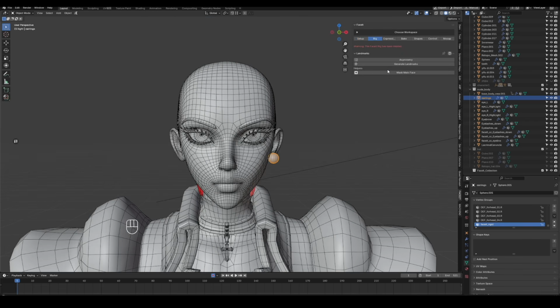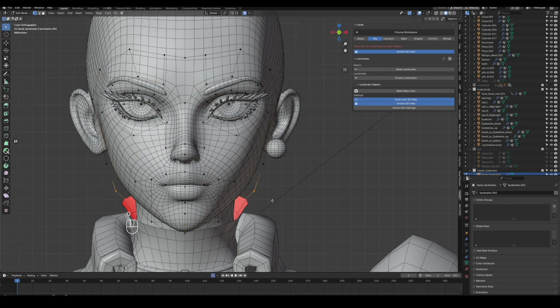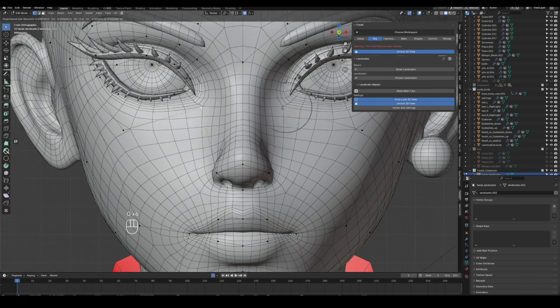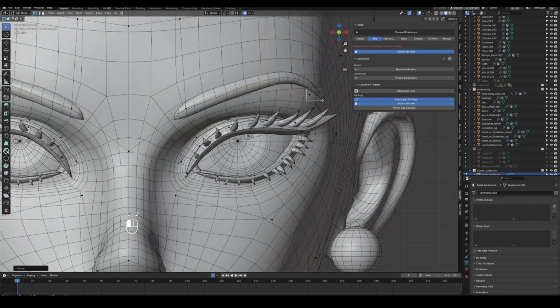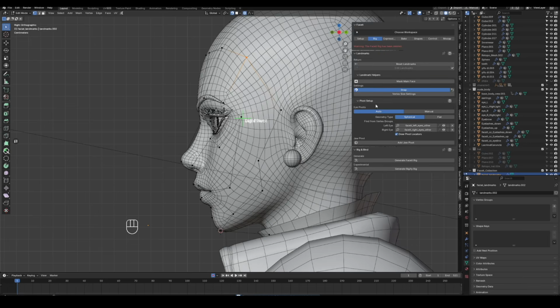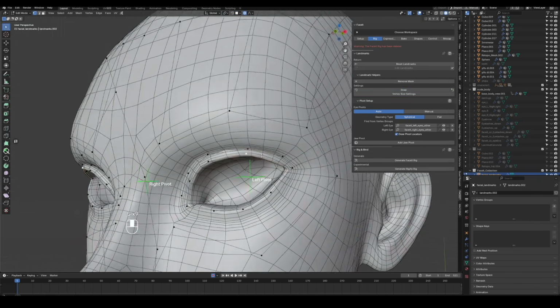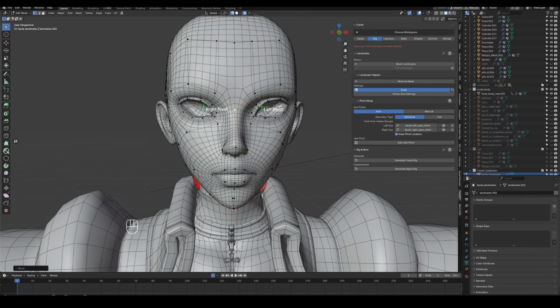Next go to the rig menu, click Generate Landmarks to create the mask, move the mask points and align them to the facial features. Once the front view looks good, click Project Landmarks, and do a quick alignment from the side too. When everything lines up, click Generate Facet Rig. Keep the default settings here, and click OK.